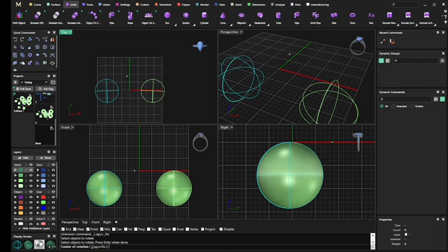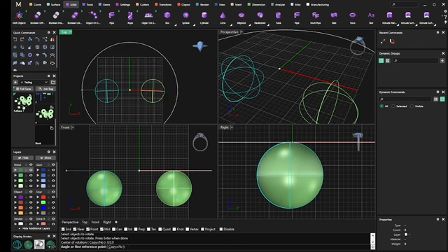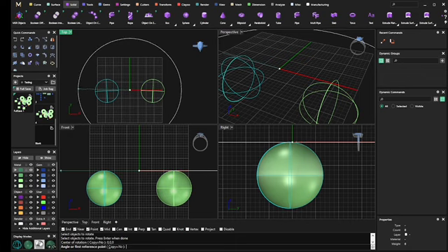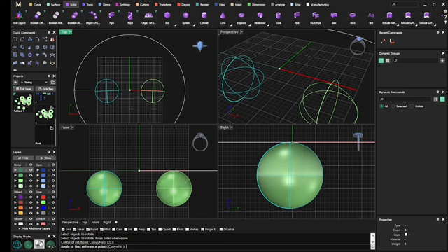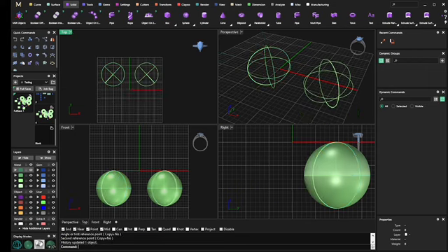My center of my rotation, I am going to press F4 because it is the center of my CAD universe. All right, so I pressed F4. Now what I usually do is I press shift and it locks it into place. And now I'm going to rotate it up 45 degrees, negative 45. And then there you go.